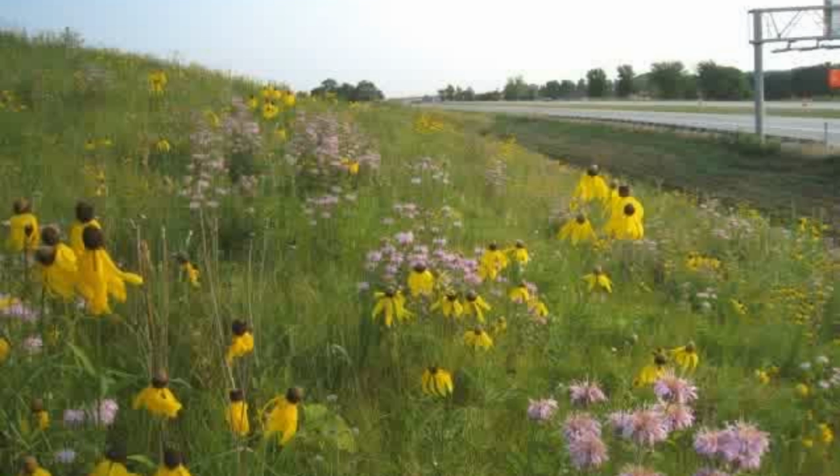Native plants and grasses are well suited for roadsides since they are adapted to local growing conditions. Native plants are particularly beneficial because they thrive in poor subsoil in post-construction areas, have deep roots that help them survive drought, compete with weeds, and prevent erosion, provide habitats for birds and pollinators like bees, require little to no watering, mowing, fertilizing, or pesticides, and are hardy enough to stand up to winter under the weight of snow and help keep snow off the roadways. This is helpful in reducing snowdrifts, which reduces plowing and salting activities.